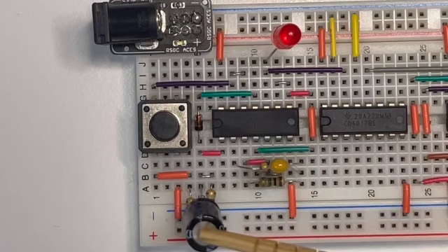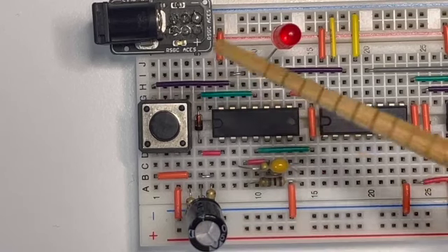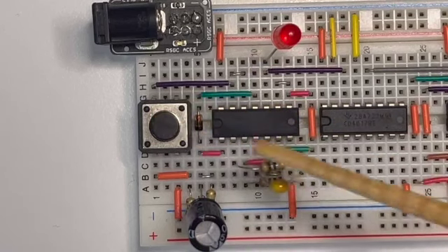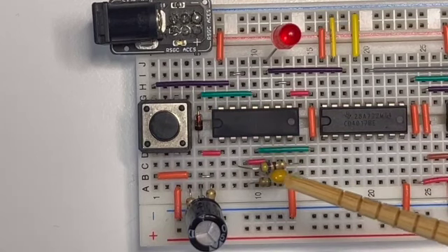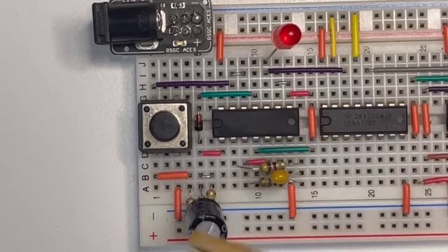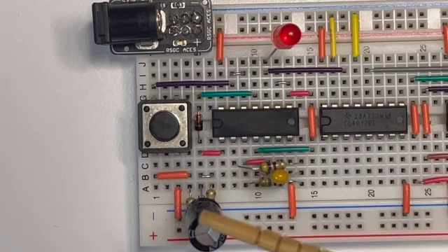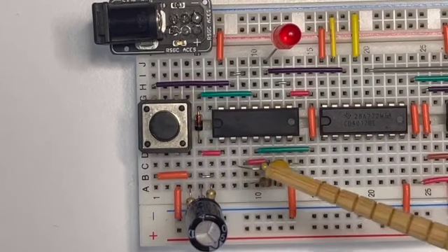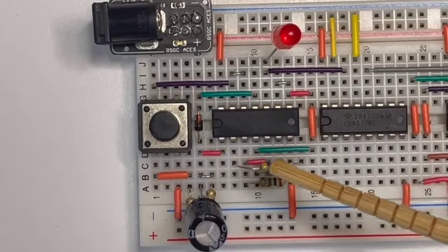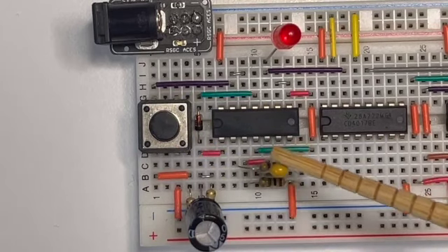RC1 is mainly responsible for how long the oscillation lasts for every button press, while RC2 determines how fast the square wave signal is being produced, at what frequency. By switching out this capacitor right here into a bigger one, we could make the oscillation last longer for every button press, while switching out this capacitor right here could change the speed of the oscillation.